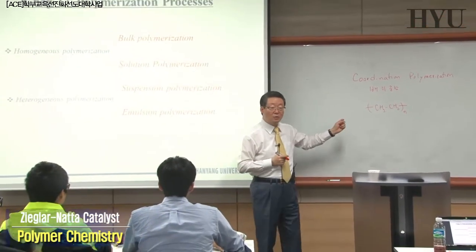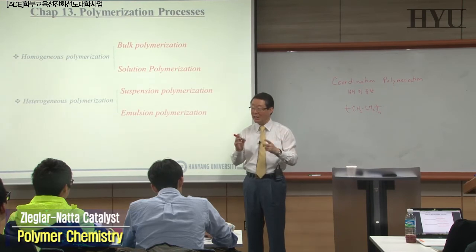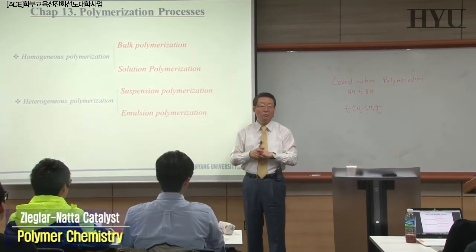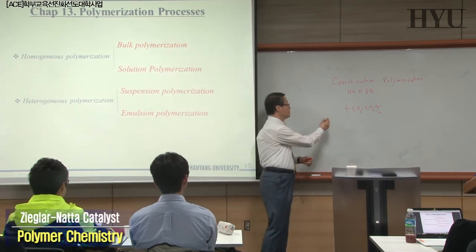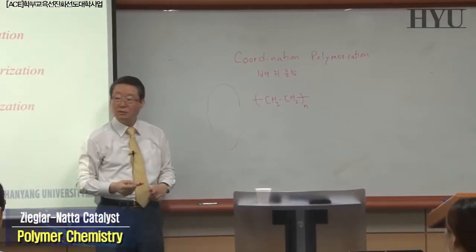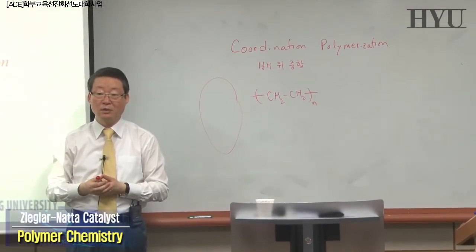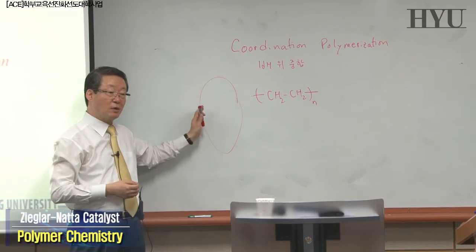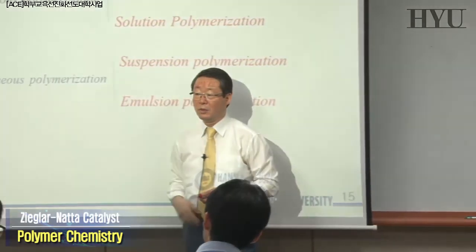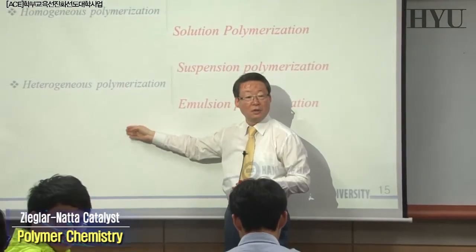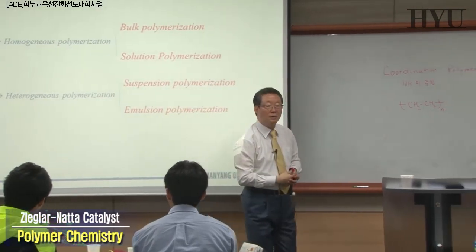Surfactants have nothing to do with the polymer structure; they just aid or assist in polymerization systems. And those other systems, other than catalyst, are regarded as external chemical components. If you add the external chemical components, we call that heterogeneous polymerization systems. Whereas if you do not have any exterior chemicals, we call it homogeneous systems.